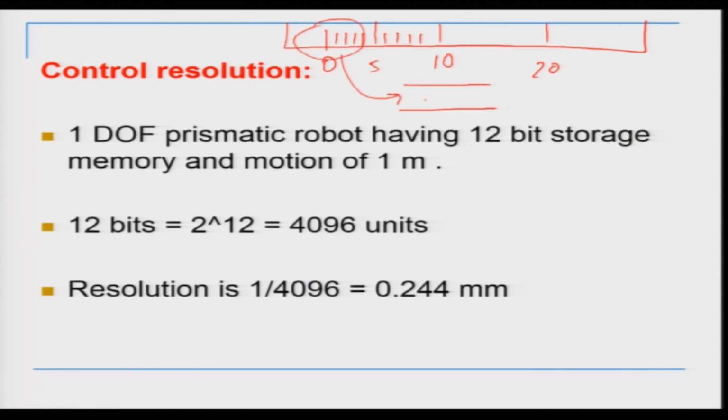So if I enlarge this part now, I am enlarging it here. What I am trying to say is that if this is my 0 and the next one is coming here and the next one is coming here, and this is my 5, I enlarge, then essentially any point in between you cannot measure, because you can measure here, you can measure here, but you cannot measure in between there. This you would have noticed in a scale. For example, if I say 10.1 millimeter you can measure, but if I say 10.05 millimeters you can't measure, because you are going in between now.